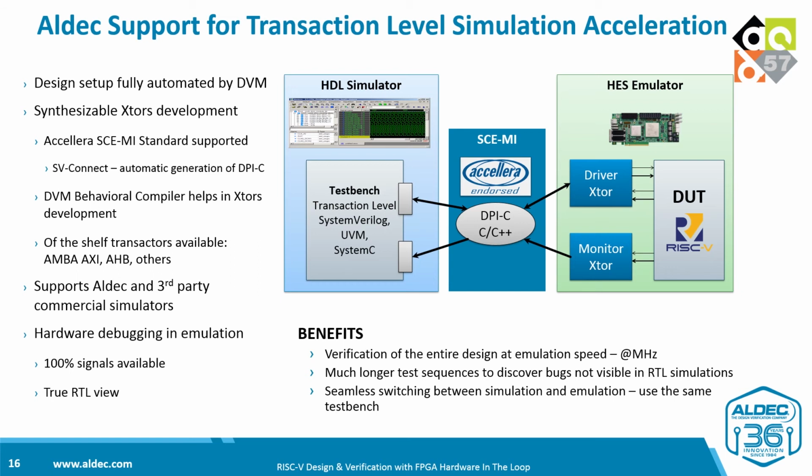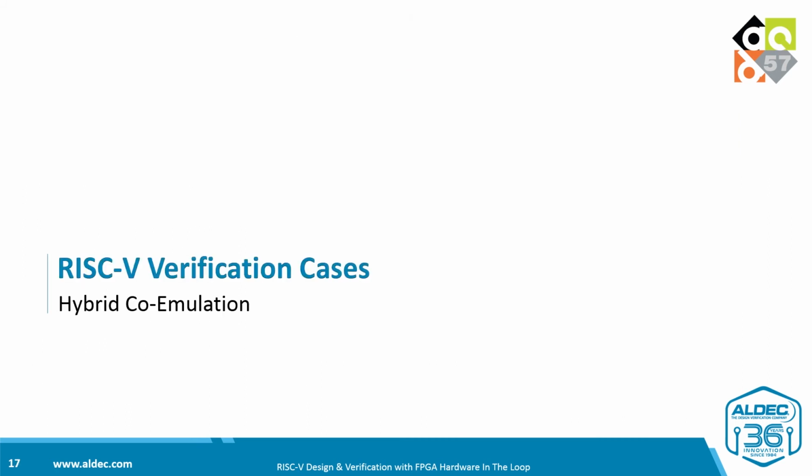FPGA-ready transactors development is facilitated by the DVM behavioral compiler, which converts non-synthesizable constructs to synthesizable form. Accelera SCE-MI support guarantees that your transactors are reusable between simulation and emulation, but also across different emulation platforms and vendors. And hardware debugger enables convenient debugging of hardware in FPGA without returning to pure simulation environment.